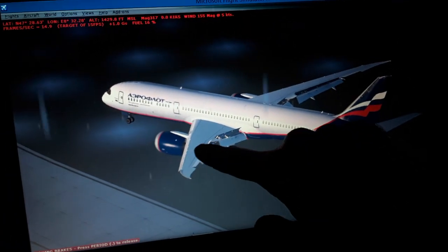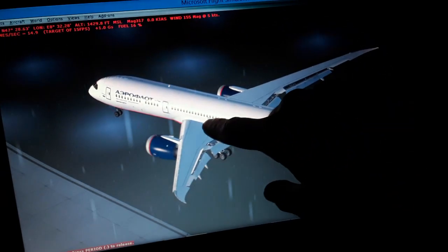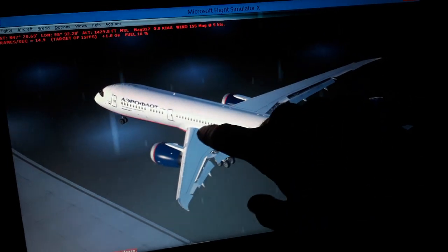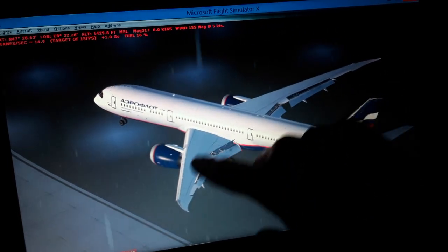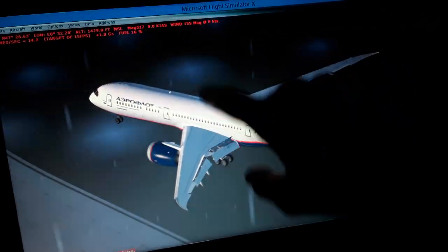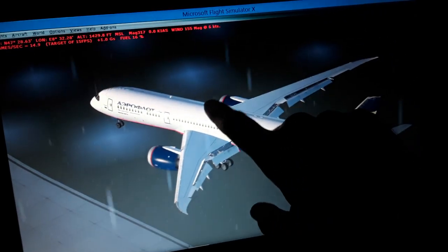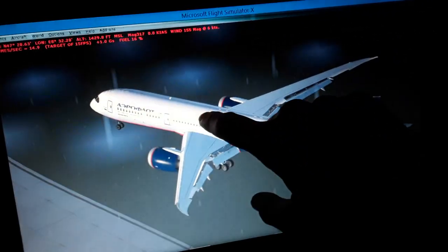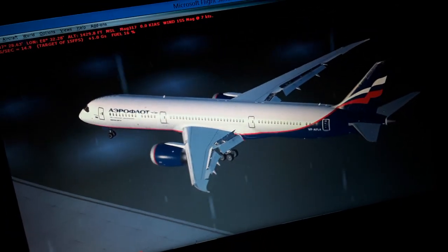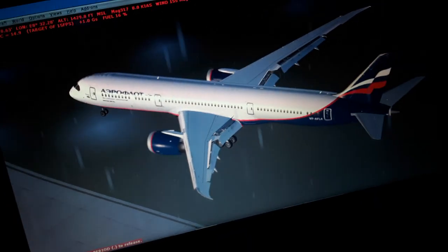So we have the principles, the tail, the vectors from the tail. We have the mean aerodynamic chord position, about 23% for this aircraft, of the forward wings. Here is the maximum aerodynamic lift created. It is also where we calculate the center of pressure behind it, and the center of gravity is approximately close to the mean aerodynamic chord position, forward or aft. We can balance the aircraft in flight. So usually it's behind it.